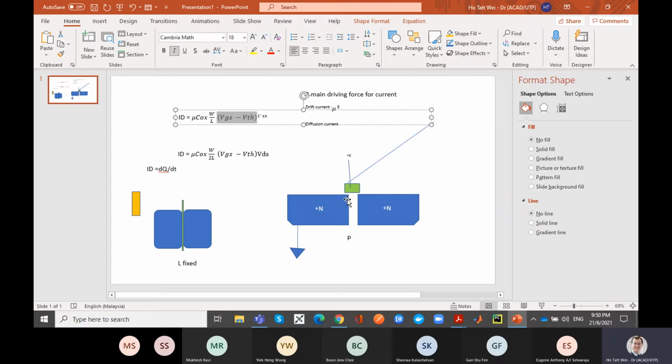And you will see once you do the mathematics that small changes in threshold voltage will give you like 2 times, 3 times, 5 times, 600% change in leakage current. But it will give you a few tenths of a percent or a few percent change in actual current.